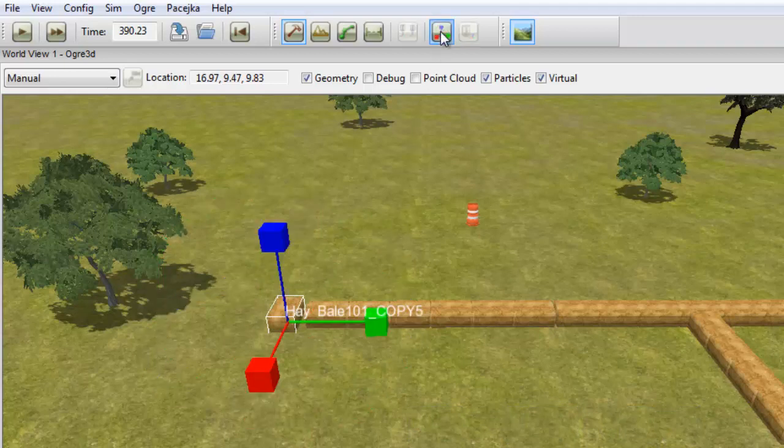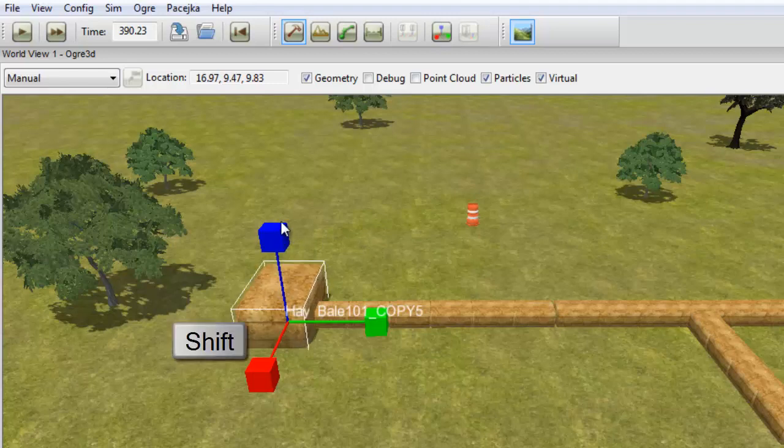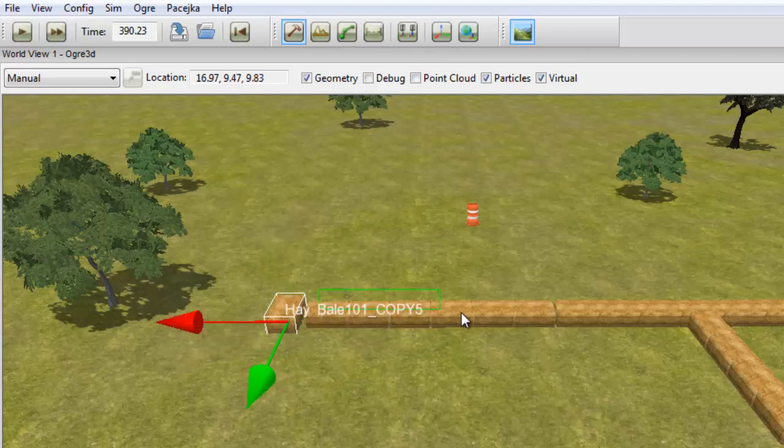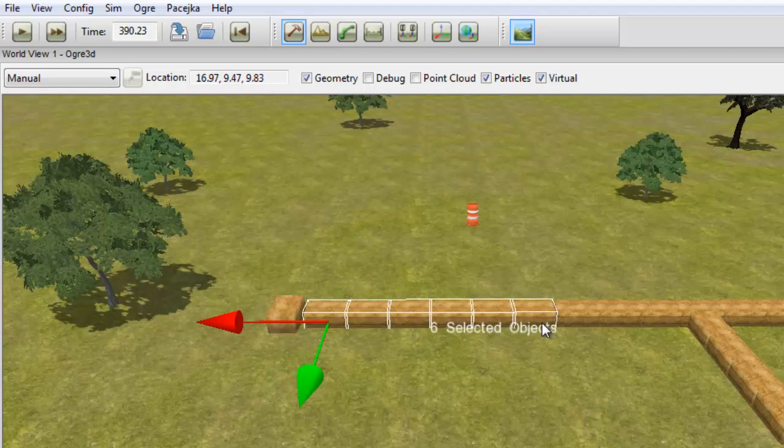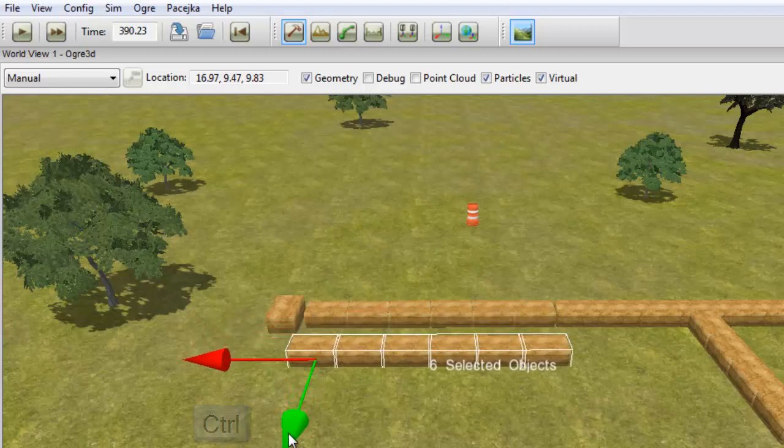You can also scale objects by dragging the scale manipulators, but not every object can be scaled. Press Shift to keep the scale ratio the same. If you want to manipulate a group of objects, you can either click and drag to select them, or you can press Shift and select them. Then manipulate them just like you did with the one object.